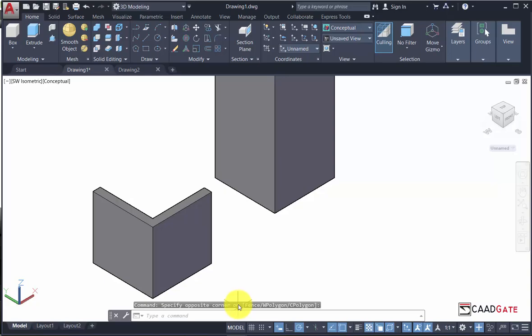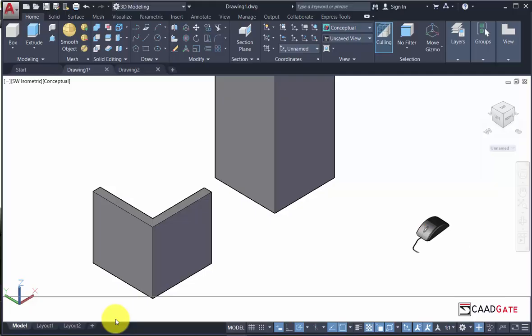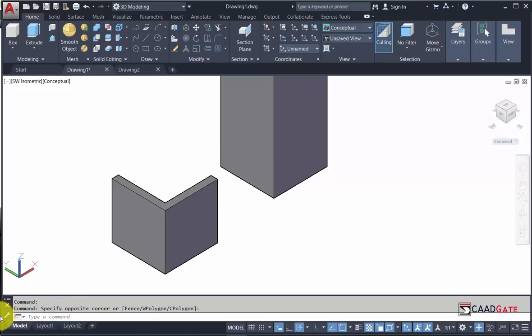So if you don't want to see it, you basically hold these grip points on the command window. Hold the grip points, drag it down. Once you notice the long rectangular appearance, like that line showing as a rectangle, just release it. Release the left mouse button, and the command window will now be permanently docked somewhere here.